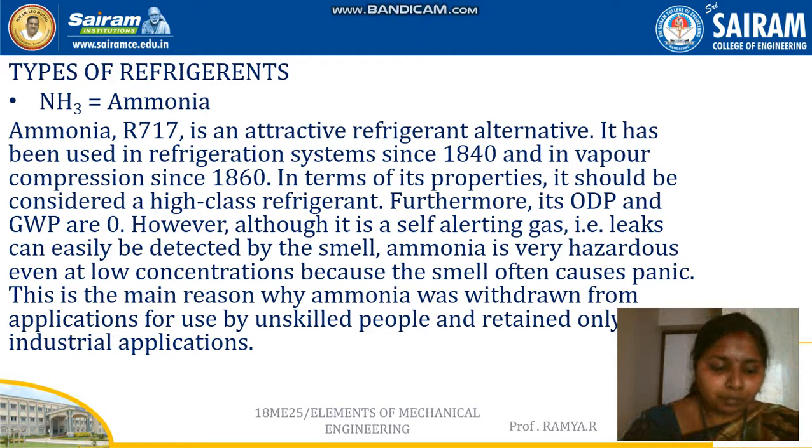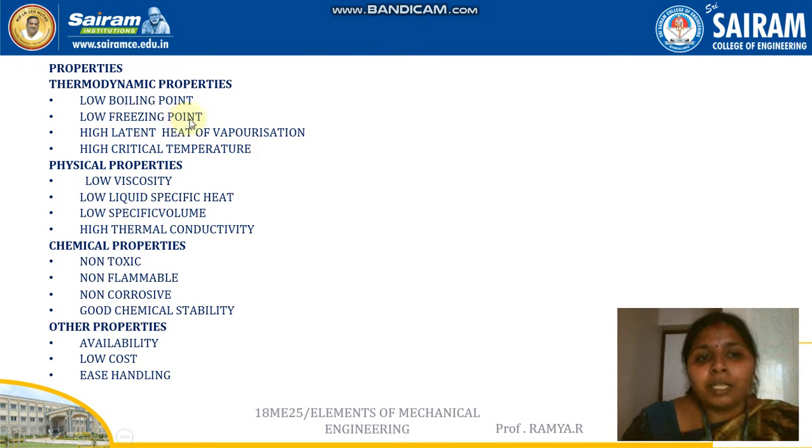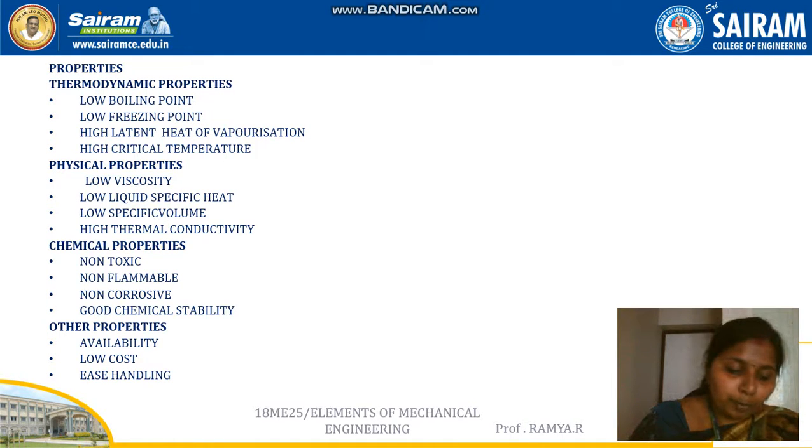A good refrigerant should have a low boiling point, below the target level. Boiling point is affected by the pressure, so the refrigerant should be selected based on the operating pressures. Next is the low freezing point. The liquid refrigerant must not solidify, so it should not freeze. There should be no solid state. Only two phase changes should be possible in the refrigerant, liquid to vapor or vapor to liquid.